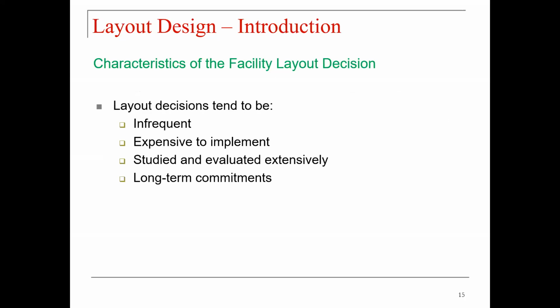Layout decisions tend to be infrequent. And you can think about why. If you're designing a building from scratch, let's say the interior of the building, you want to make sure that you make those decisions carefully because those are going to be fixed for a long period of time. You don't want to be moving machines, connections, pipes frequently, right? So that's why we say that these decisions are infrequent. They're also expensive to implement. And that's why they're studied and evaluated extensively, because they require long-term commitments.